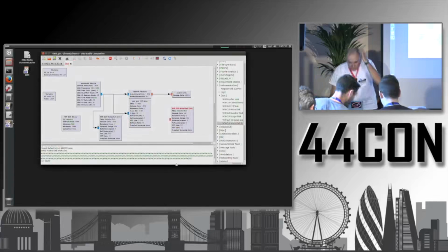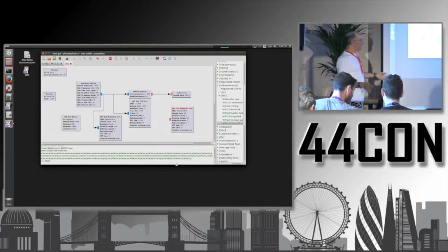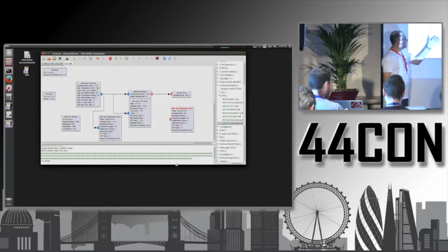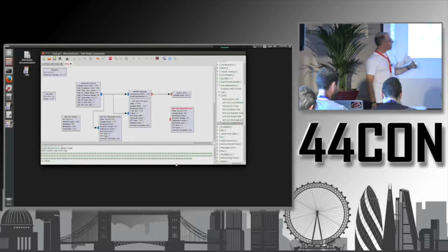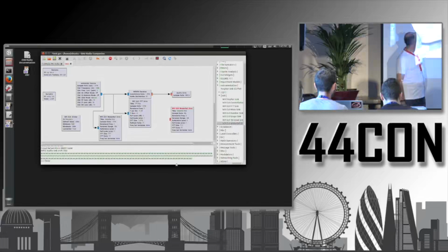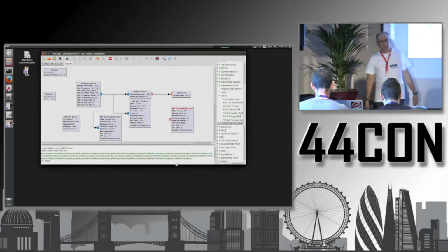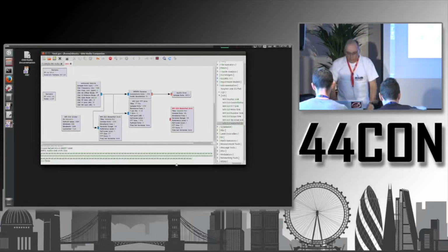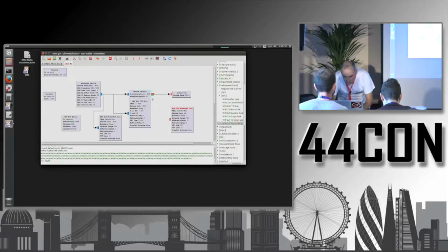So those are things you always have to pay attention to with software-defined radio here in GNU Radio: the sample rates of the different components and also the impedance matching. And now that I've configured my second waterfall sink like that, I can connect the audio like this.